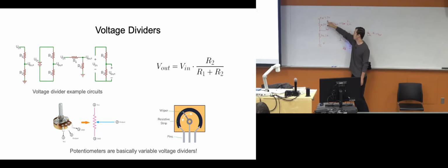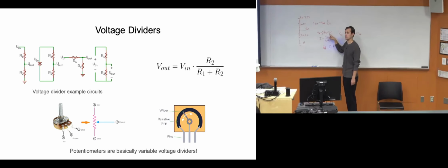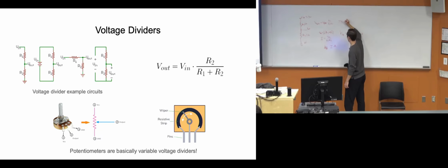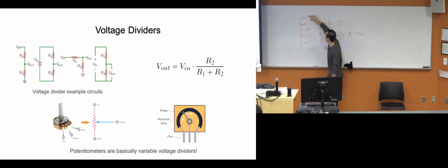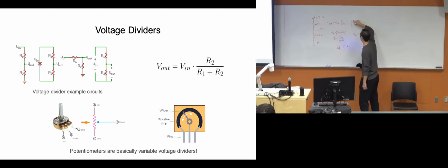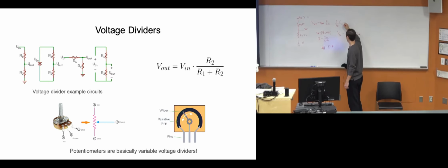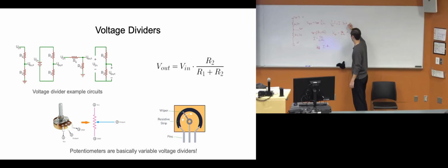So this voltage should equal the current going through both of these resistors, right? Because they're in series. So we can solve for the current here. So we have 3.3 volts divided by 1K plus 2K. Actually, I'm going to make this 3 so I have to do less math. By 3 kilo ohms equals our I. So that gives us 1 milliamp.